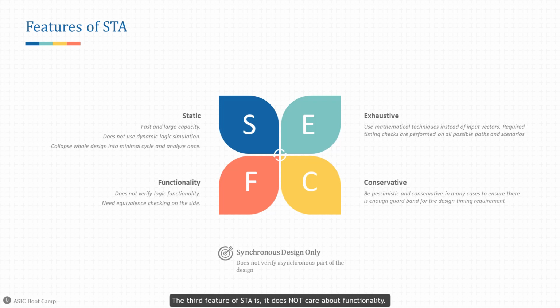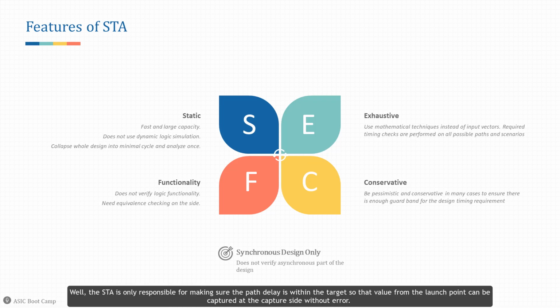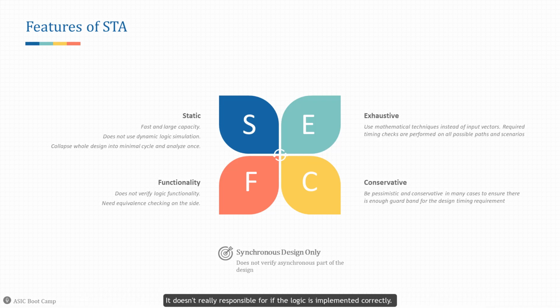The third feature of STA is, it does not care about functionality. Yes, you have not heard wrong. How can such a powerful thing not care about functionality? What if the design meets timing but has functional failure? Well, STA is only responsible for making sure the path delay is within the target so that the value from the launch point can be captured at the capture side without error. It is not really responsible for whether the logic is implemented